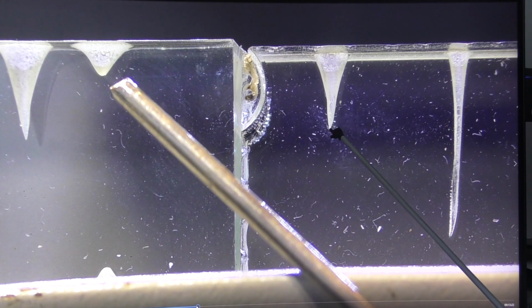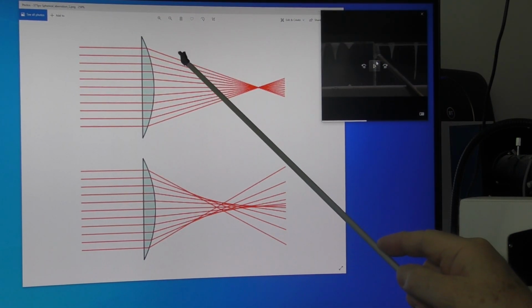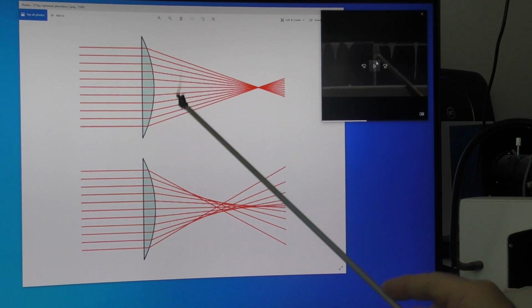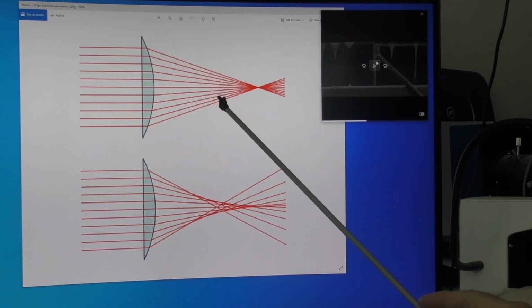This again is not a focal point. This is just a point of high intensity light. And then when we move to 120mm, roughly 2/3 of the way down the beam, look, we've got a much smaller entry, because the beam is smaller at this point because it's beginning to be focused, but it's not focus. And this point down here is not a point of focus. This is damage caused by the intensity profile at the surface. Having passed through a lens, we're sampling the intensity profile across here. And then with this very thin one, we're sampling the intensity profile here.